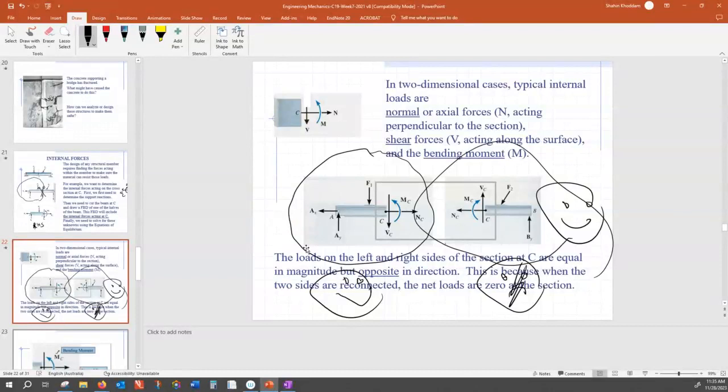If you take the left-hand side, then we have to determine the shear force first, and if it's positive, that determines the moment as well. If your answers become positive with that assumption, it means your beam at that particular section is positive, then everything else follows along. If that assumption proves to be wrong, it means your beam is not a positive beam, it's a negative beam.